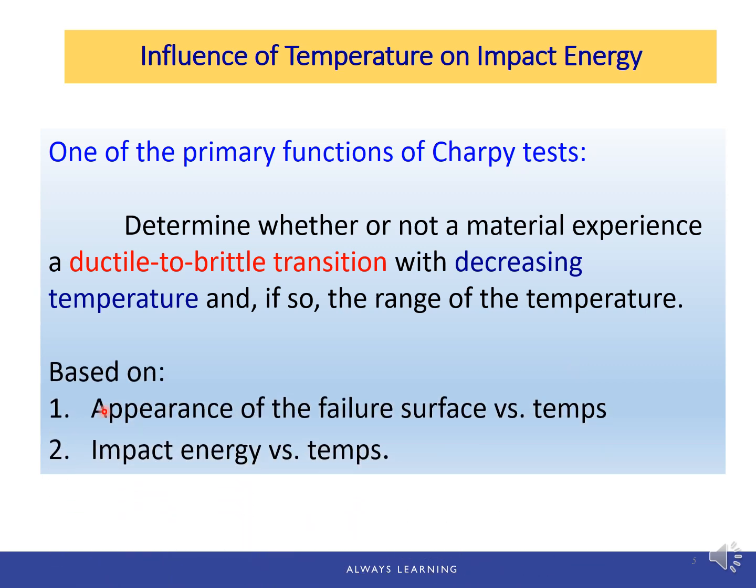There are two ways to figure that out. One is by the appearance of the failure surface or fracture surface versus temperature. And second, we plot the impact energy versus temperature to see the transition from ductile to brittle.